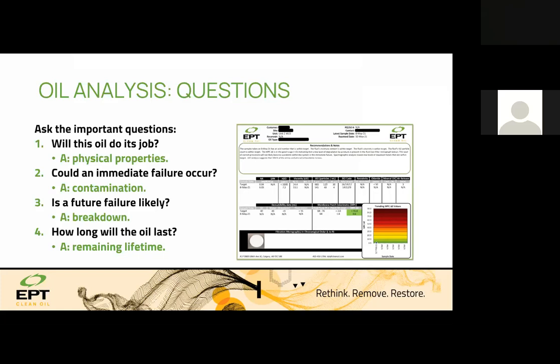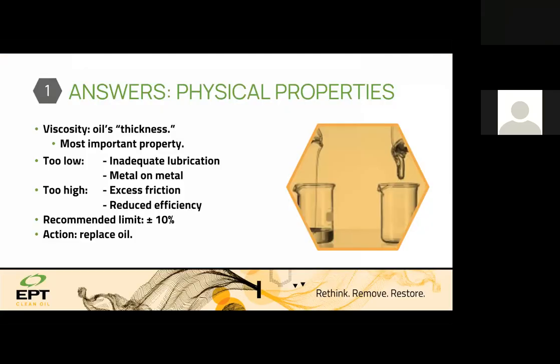Once we know the breakdown is happening, acid number is going high, we have varnish, we have a lot of particles, then we need to know how much remaining useful life the lubricant has, how much further we can use it until the first maintenance shutdown comes, or the chance of filtering or doing a top up, for example, to take an action, how much time we have. So will the lubricant do its job?